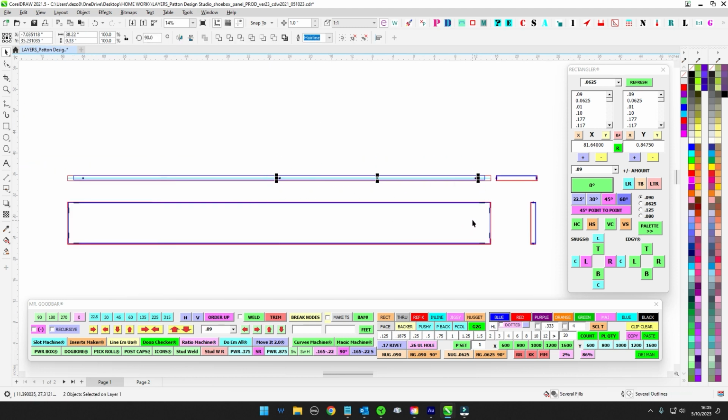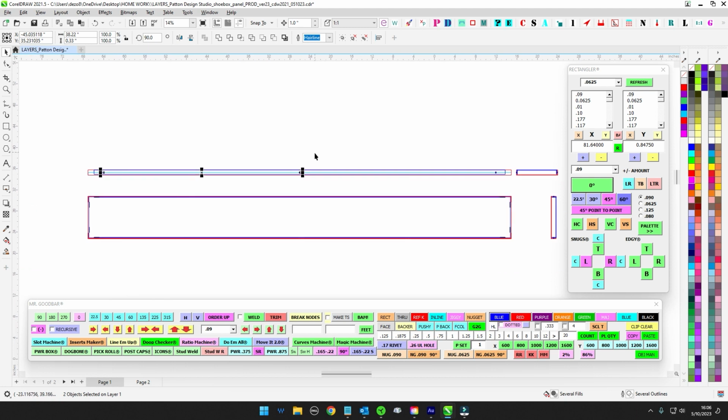Now this brings up another thing. If you're going to do this, you've got to understand UL. You've got to be read into the program. This doesn't need to be UL, that's fine. But if you're going to do this for UL, the maximum distance between fasteners is 24 inches. You have to have a fastener on center every 24 inches or less. As the material gets thinner and thinner, the distance between fasteners gets shorter and shorter, down to the point where super thin metals require a fastener every 6 inches. It's ridiculous, so you've got to keep that in mind.